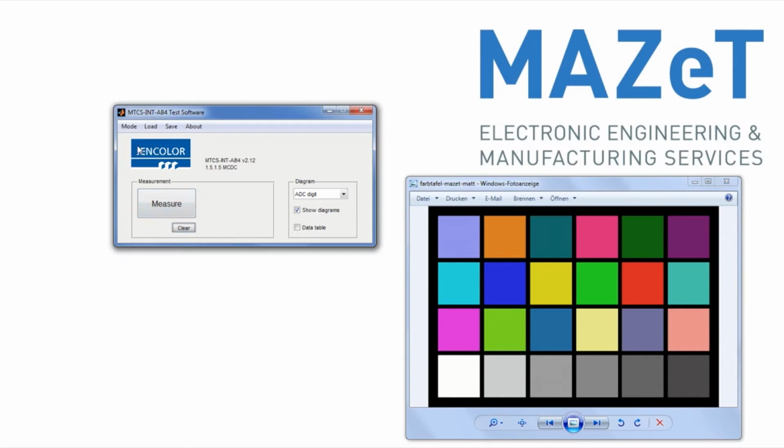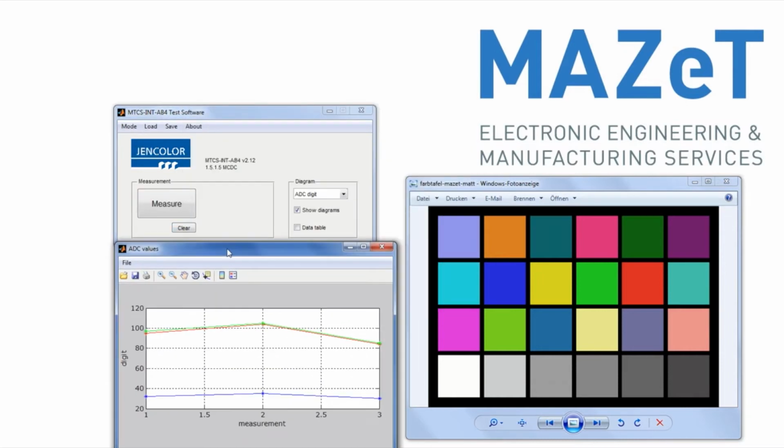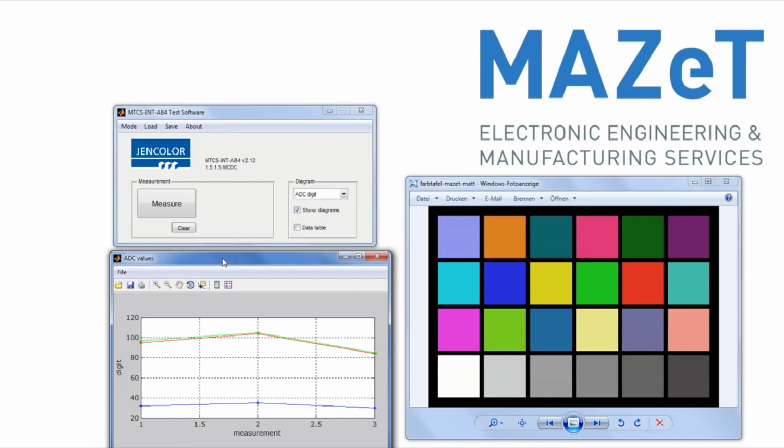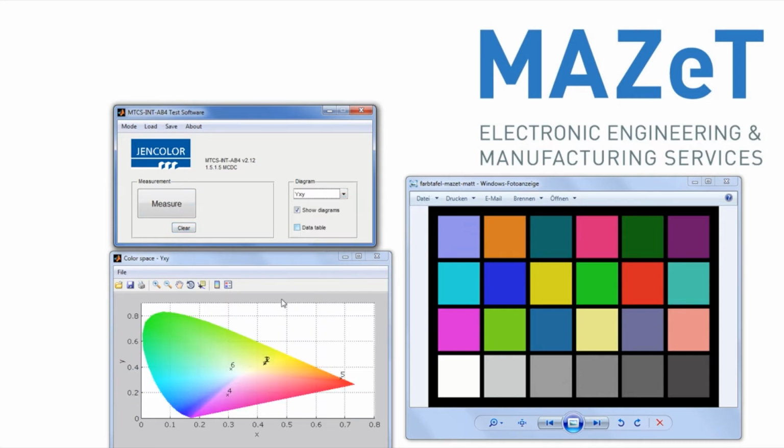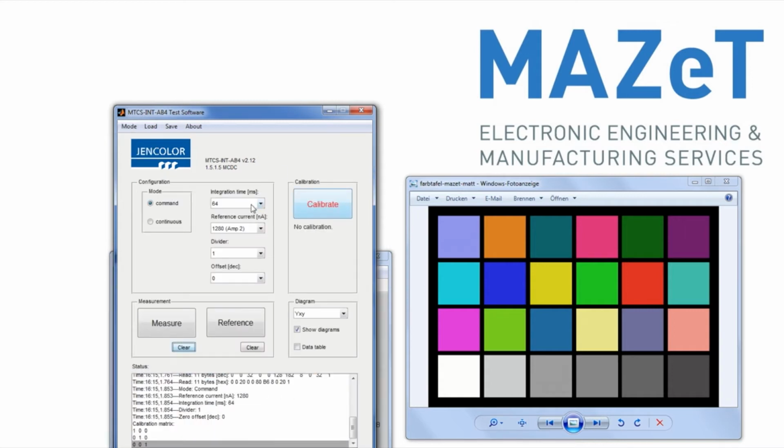It is important to know that each application is different, and therefore calibration is required. The device offers an easy mode that can be used to initially test the system, for example, using a computer monitor. Keep in mind that these measurements are performed uncalibrated, and differences in accuracy can happen. This mode allows to perform simple measurements. Use the drop-down menu to change the output from ADC digits to color spaces to see how the color measurement is performed. The next steps will explain what needs to be considered during the application calibration and how to perform it.